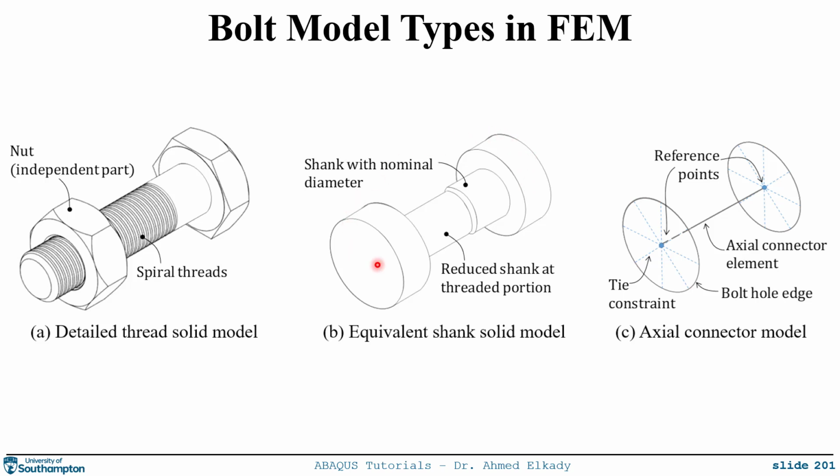In this one, you will need to define the material properties and the stress-strain behavior of the bolt. And if you want to include damage, you need to calibrate the material parameters for the damage to simulate failure in the bolt.